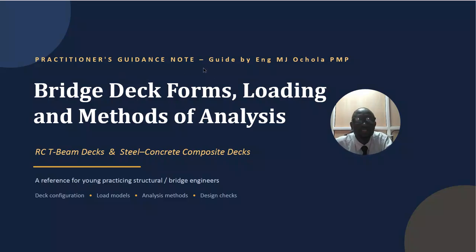Practitioner's guidance note. So the bridge deck form. I've already posted a lot of the deck configuration to you guys to appreciate. So you just look at reinforced concrete T or I girder; we can look at reinforced concrete without precasting within up to 15 meters. Then beyond that you can do precast. Then also steel concrete composite. So we already shared some textbooks and he's going to share more tomorrow.